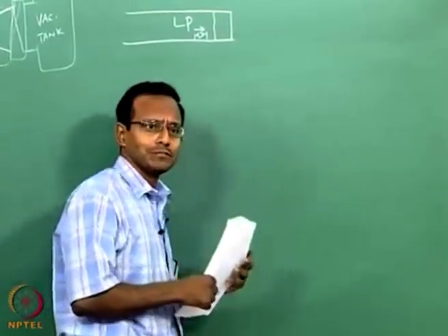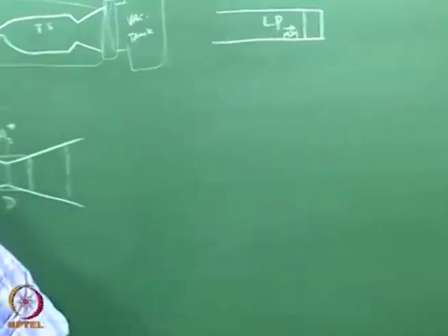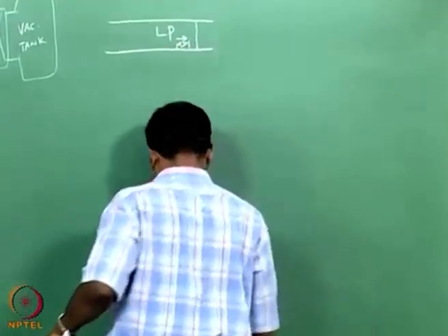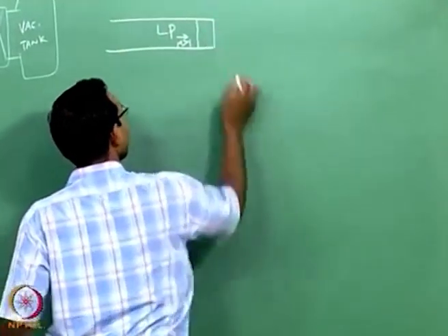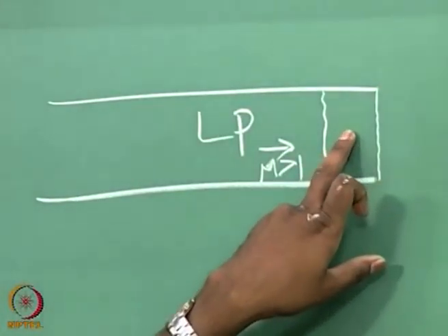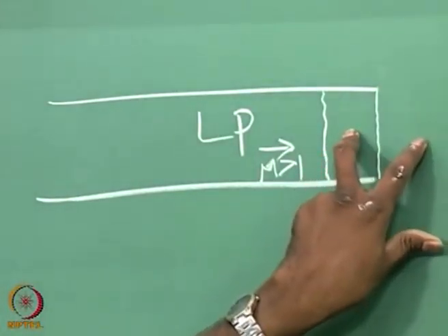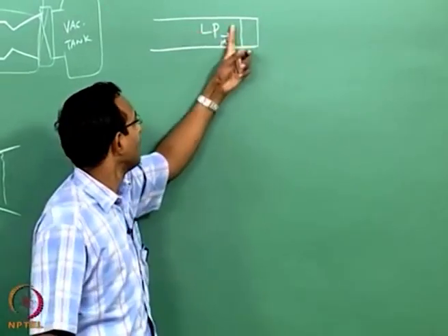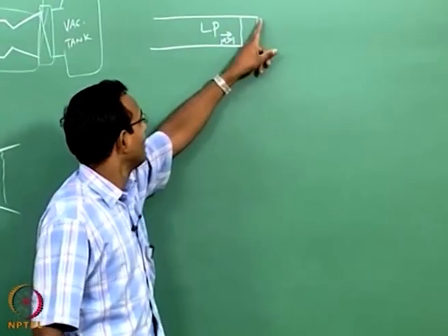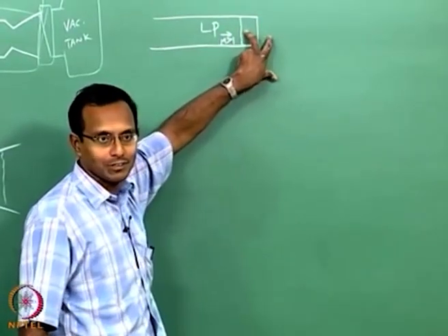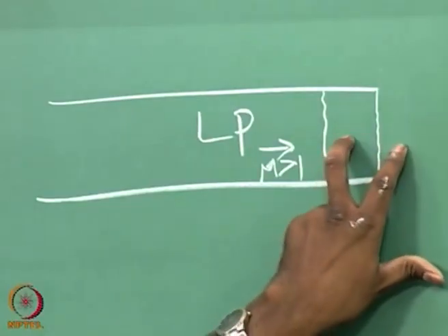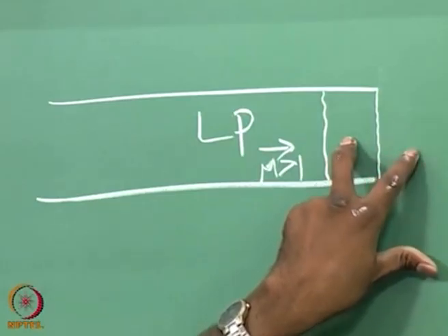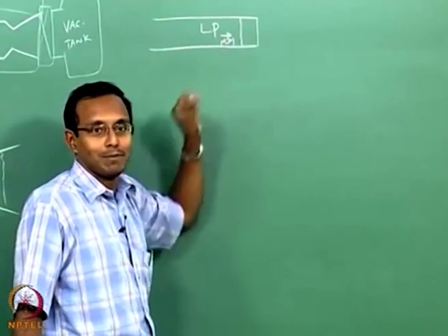If I have such a situation, now if I put a thin diaphragm here which can hold low pressure difference across this, but not the post shock pressure. Then what will happen when the shock reaches here? Immediately the diaphragm experiences huge pressure difference across it and the diaphragm ruptures. Typically people use thin plastic sheets there. If I use thin plastic sheet, one side is very high pressure, other side very low pressure, it just gives up, it cannot stand there, it will be like a balloon bursting.